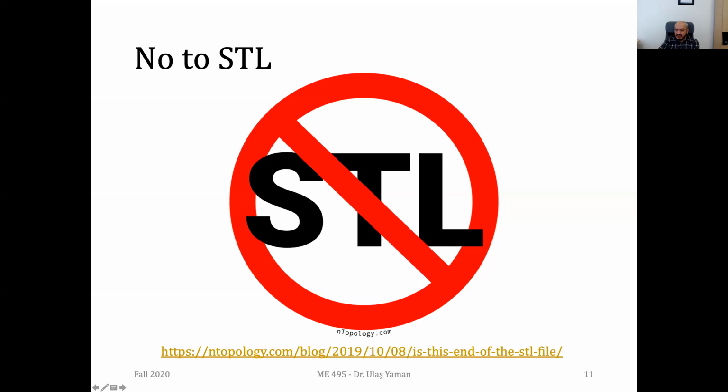I think we have another question. Yes, even though you have the vertex information in 3D, you need to define the normal vector. Since by using the normal vector, you define which side is actually the outer side of the part. For instance, if you have such a normal, then that means the opposite of the normal is the interior of the part. This is important information for us. If you define the normal interior, then I will assume that the interior of the part is the opposite of the normal. So that's why for each triangle, we need to define the normal and the vertices.